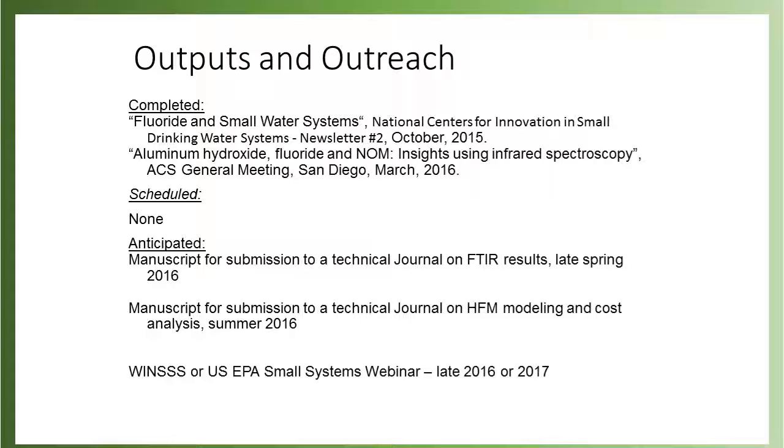Yeah, but when you have a full-scale ED system, we were using 4 cell pairs, they use 100 cell pairs, and basically the amount of energy you lose at the electrodes becomes a negligible fraction. In this system, it's a pretty high fraction, but that's really irrelevant for total operation. Instead of straight ED, especially for smaller systems, capacitive deionization is out there, which is similar in concept to ED, but you're saving a good chunk of the electricity.